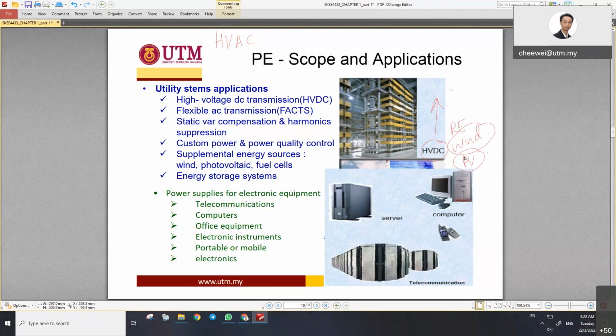Because the countries in Scandinavia have different standards, to transport from one country to another requires different standards and different synchronization. So it's quite difficult, so they do HVDC. Another reason is cost. For long transmission, from one country to another, it's a very long transmission.